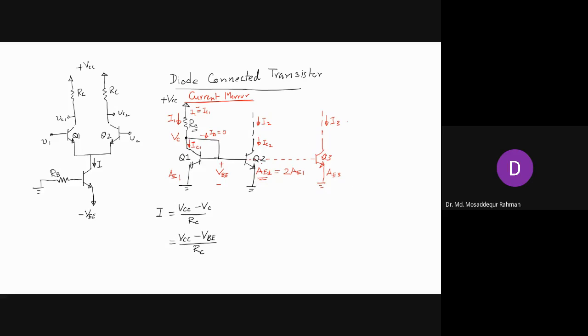Like if you think about the multi-stage differential amplifier that we have discussed, that has the input stage, gain stage, the output stage, and all those stages will need different amounts of current. So instead of using this one here, which is just one single unit and cannot be extended, we can use this current mirror circuit to generate a current first, and then reproduce the required amount of current by choosing the appropriate area of the emitter cross section, and supply it to the different stages, right?